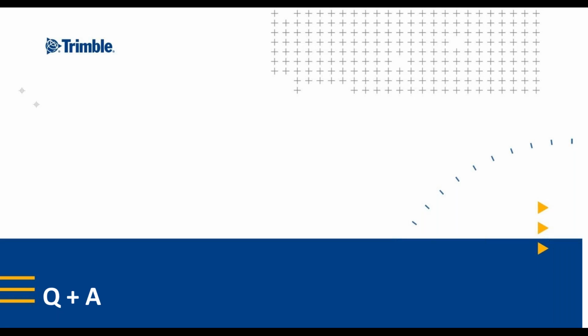To do this, you would do a combination of what Adam has shown. You would import your GNSS data. You would compute your local site based off of that GNSS data in your project location. Then you would import your total station data and complete your site cal from there. So that step of using the local site first would bring your grid plane up to your ground plane.